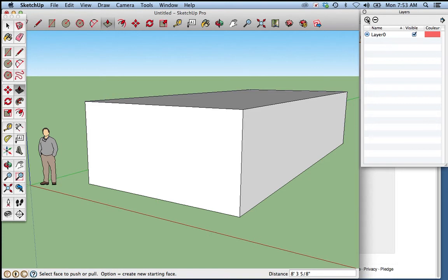I'm going to make a new layer for what I'm doing next. I want to make a roof layer. Now in layers, you'll see it, you can make it visible, but you've got to pay attention to what's active. I'm going to make this roof layer now active. I'm going to delete this top, which looks like the roof, and I'm going to build a new one in the roof layer. So I've selected it and the button's blue.